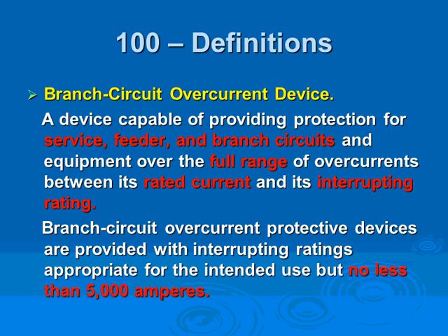Circuit number 1 is the conductors coming from the utility transformer and dumping that power into your building. These are called service entrance conductors. That's circuit 1. We brought the power to the building, the first disconnect, the first service equipment. From the first disconnect service equipment, we distribute that power inside your building, between panel A and panel B and C and D. These are called feeders. So here's the feeders, we protect them too. And the last one, from the 20 amp circuit breaker into that light, that's called your branch circuit. Or from the 400 amp into the air handling unit, or chillers that you have, that's your branch circuit.